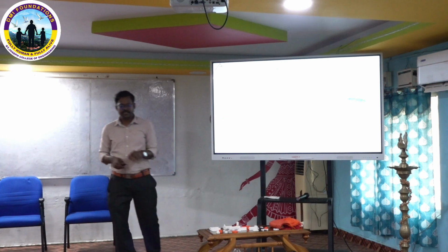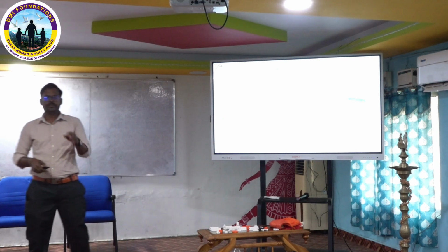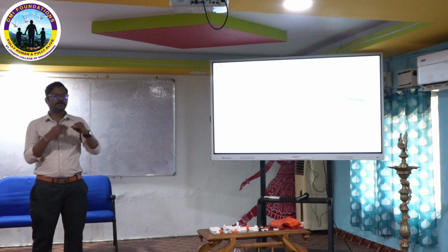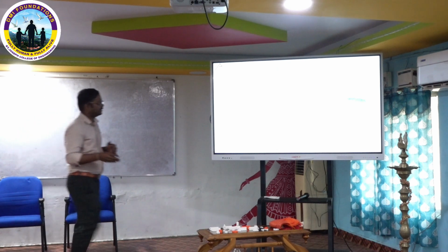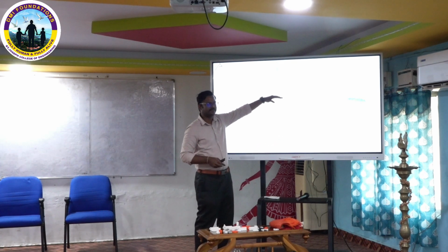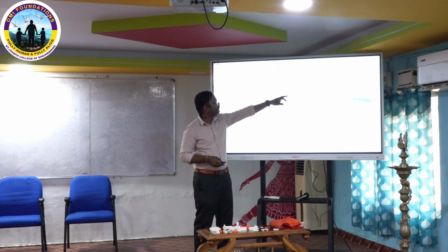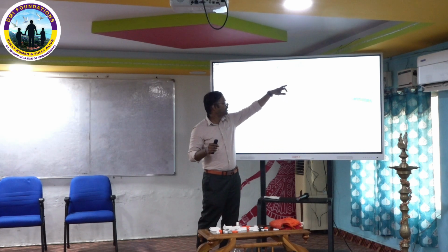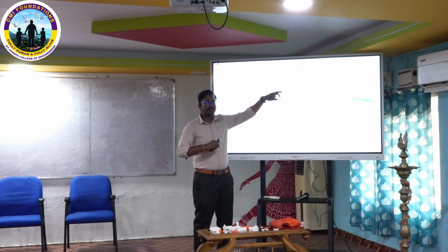Boundary condition is nothing but how the test is going to happen, what load conditions I have to apply, where the component is going to be fixed, all these things I have to define. For example, I am going to do a compression test for this cube lattice structure. I have to fix the bottom plate, so I have to give a constraint there. Then on the top portion I have to give the compression load.